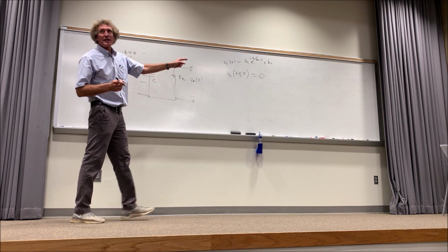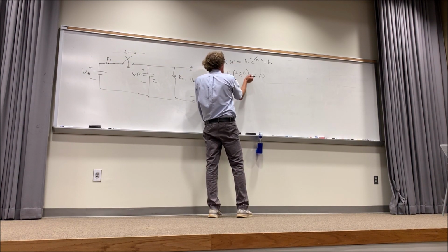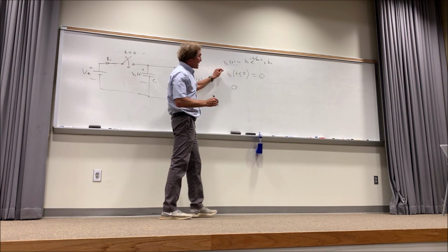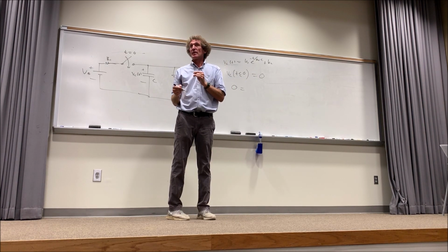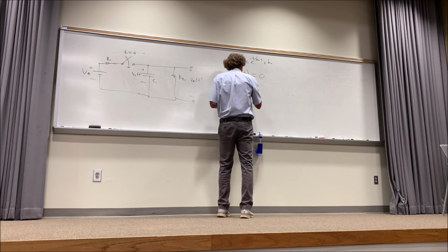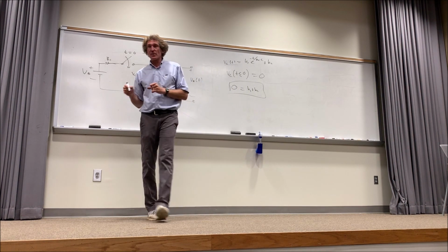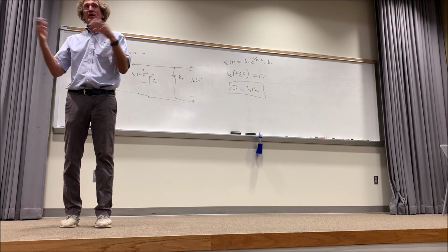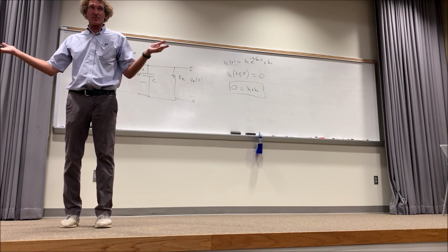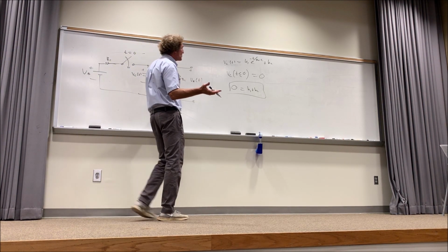Now, why did I say that? Because now I can go up here and say that Vc at t equals 0 is 0, right? You all see that that means this is 0, right? It is equal to what? Well, it's e to the 0. What is e to the 0? 1, right? So it's just k1 plus k2. Ah, great. You've got one equation with two unknowns. This is like differential equations back in the day. You get the general form, and then you use the boundary conditions to solve for the constants. Remember that? So now we find the other constant; really, we find two equations.